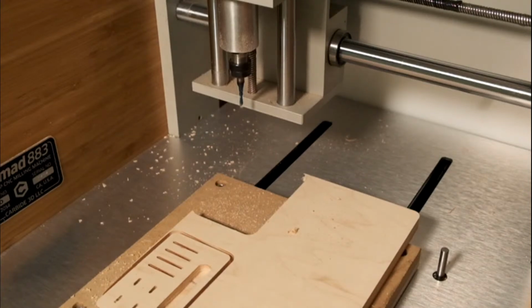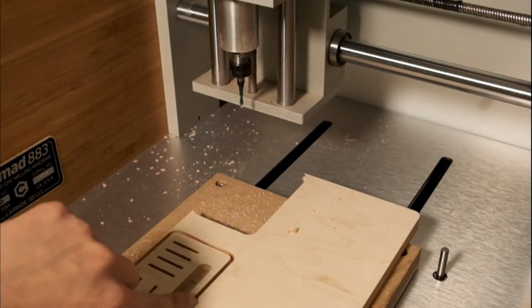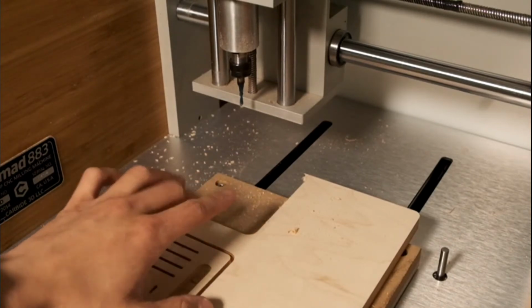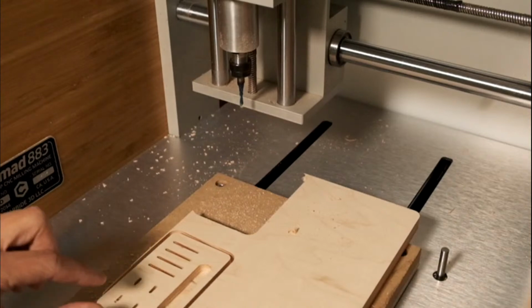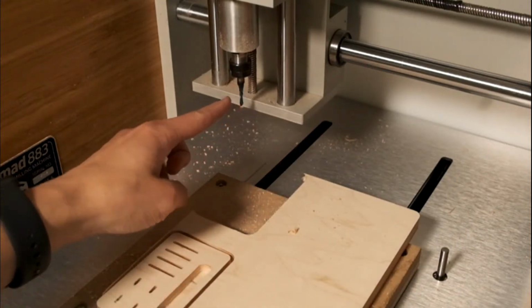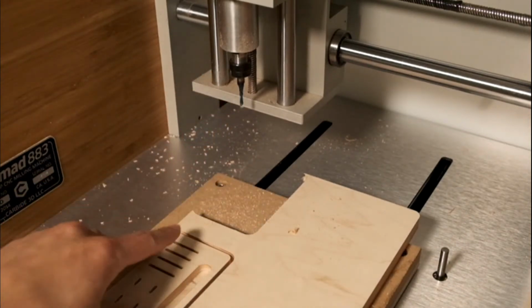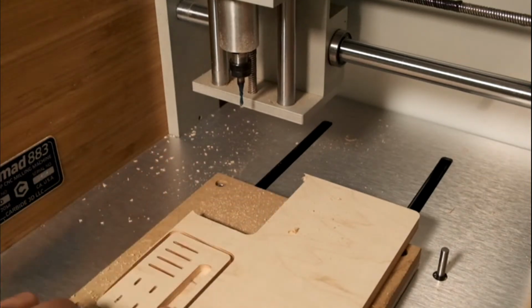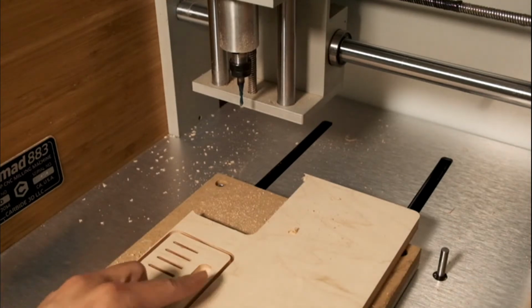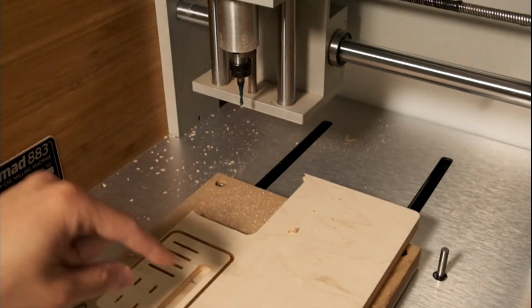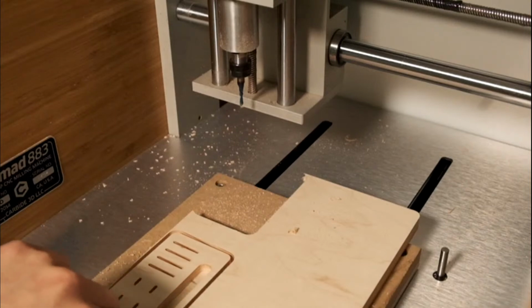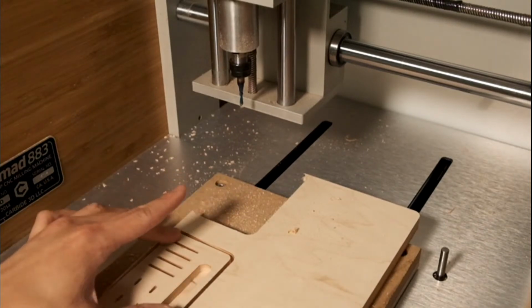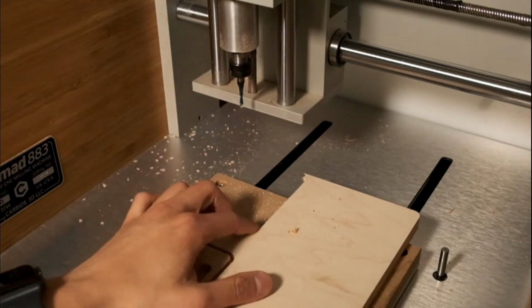All right, we're back up to volume. So you might have heard the cuts towards the end in here and here get a little chattery and violent. That's just because downcutting end mills in general don't do a great job of chip evacuation. It's literally just packing sawdust deeper into the cut and making it harder for itself to push through. That's why I was coming in with the vacuum a lot more frequently towards the end. An 1/8" upcut wouldn't do that, but then you also wouldn't have this clean surface on the top. So that's kind of why I wanted to do the 1/8" down cut.